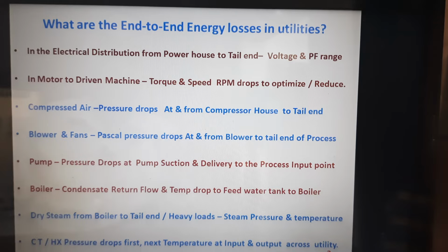Coming to the cooling tower or the heat exchangers, normally all of us monitor the temperature drops, the temperature difference across the cooling tower or the heat exchanger. That is more important, but it is more influenced by the pressure drops across the cooling tower or across the heat exchanger, which decide the temperature drop across the given utility as such.